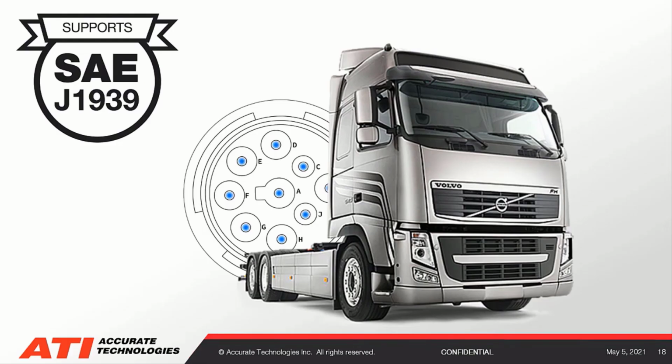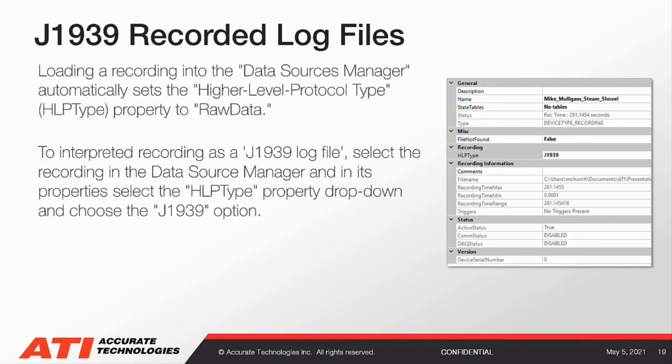There are a few things to keep in mind when using CANLab with J1939, such as setting of the recording protocols and assigning the database files to the proper channels. By default, with the J1939 recorded log file, CANLab sets the high-level protocol to raw data. To properly decode this, it needs to be set to a J1939 format.